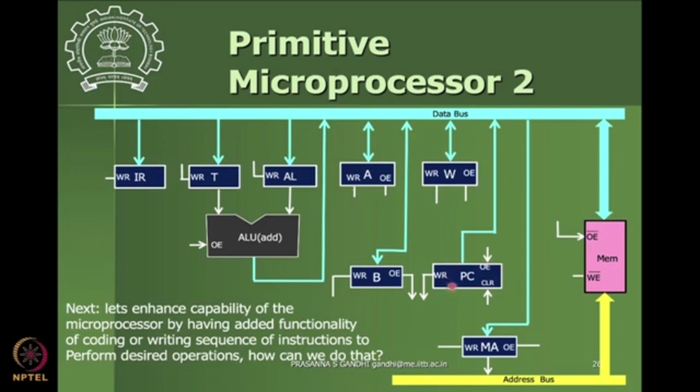Okay, it will fetch the instruction first, whatever you have written in that program, and it will put that into the instruction register, which is another facility that is there. This is a special register. There are some special registers having special functionalities in the microprocessor. Typically, not all registers can be accessed by a user. This is very typical for any microprocessor.